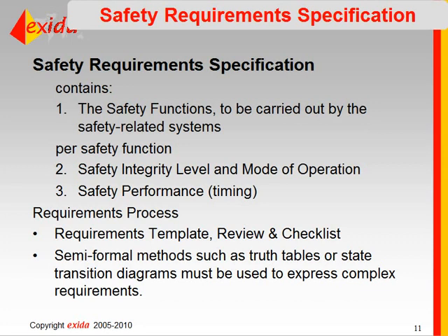And then per safety function, you have to define a safety integrity level. So 61508 defines 4 safety integrity levels, SIL 1 through SIL 4. SIL 4 is the highest, SIL 1 is the lowest, and essentially that is related to how much risk reduction you're looking for in a safety system. So a safety system essentially will reduce the risk of a hazard.